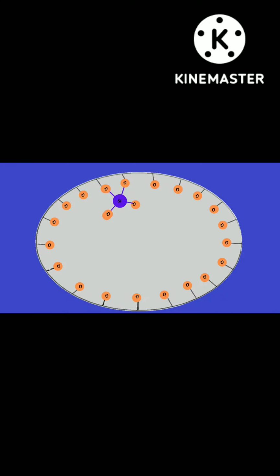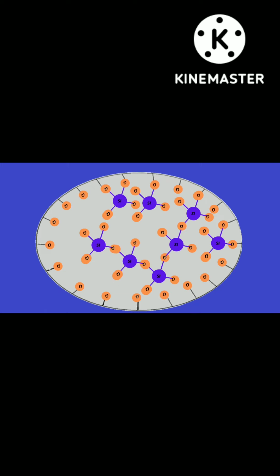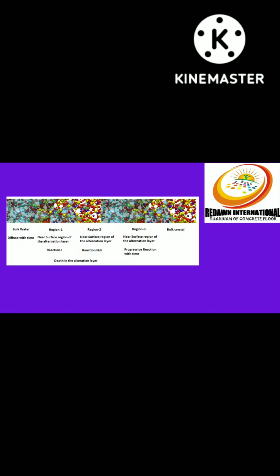The liquid has very low surface tension and carries particles below the surface. The pure silica particles have a relatively higher proportion of reactive sites than silicates, so they react very efficiently. In the pores, colloidal silica creates new calcium silicate hydrate that bonds to the existing calcium silicate hydrate. Colloidal silica also bonds directly to other silica, including itself. When applied to concrete, it reacts, makes a bond and then uses that bonded silica as a platform for additional bonding. Sodium silicate densifiers do not do this.